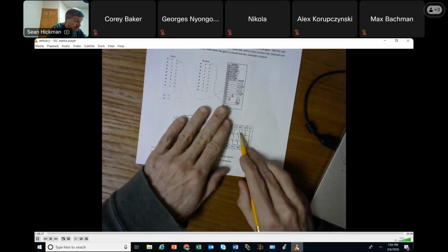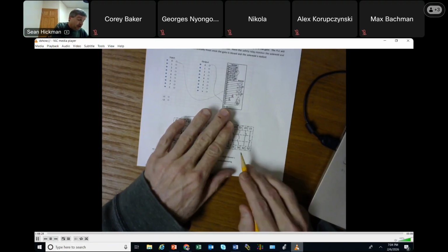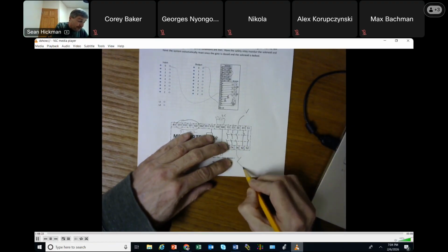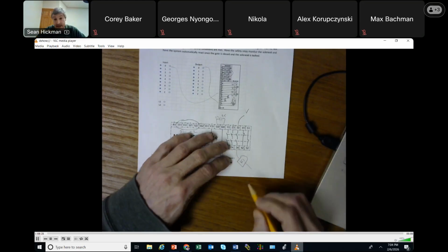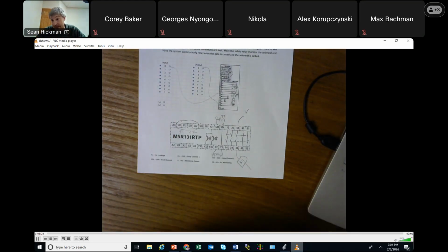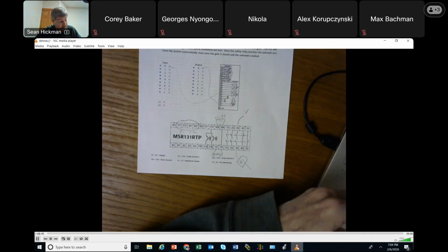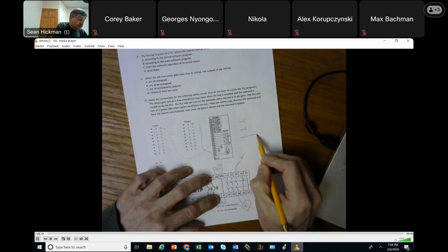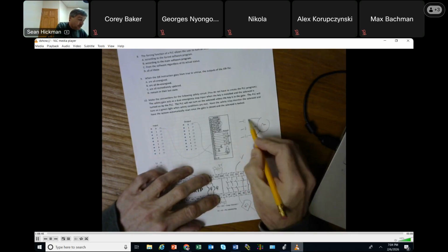And then finally, these are the big kids here. This is passing voltage here to whatever we're trying to turn on. If it's a contactor or something like that, or the PLC module or whatever, that's the device. And in this case, it was a motor. So we were turning on a motor like this with K1.